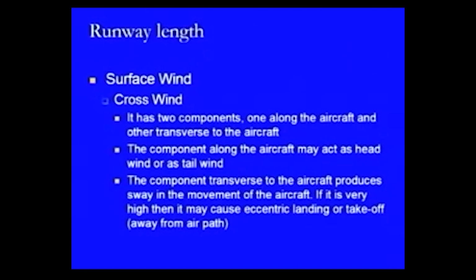If this component is very high, then it may cause an eccentric landing or takeoff condition on the landing strips or the runway, or at the same time it may also cause a drift of the aircraft away from the flight path, which may be dangerous because there may be another aircraft using an adjoining flight path in the space, and it may cause a collision at that point.